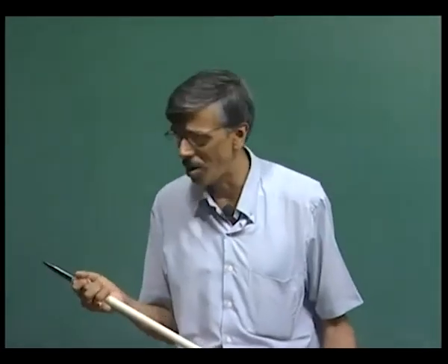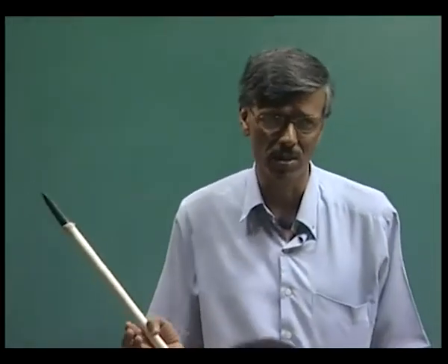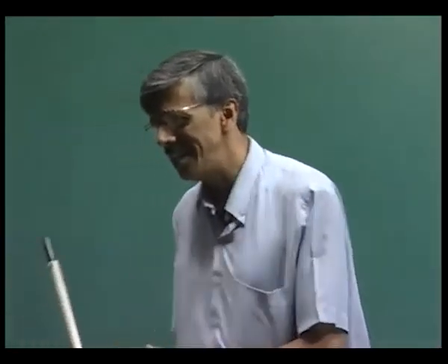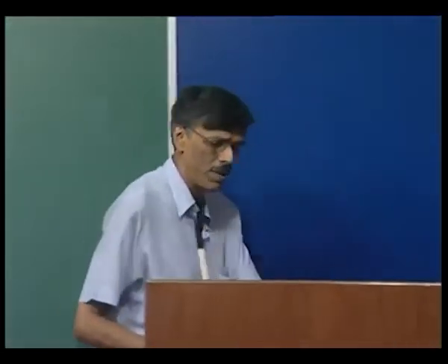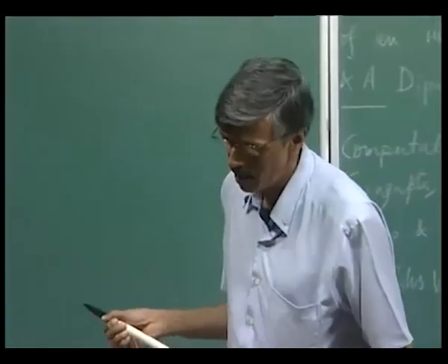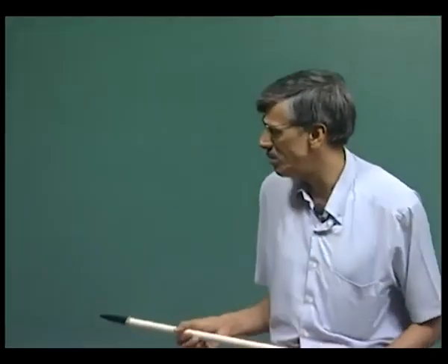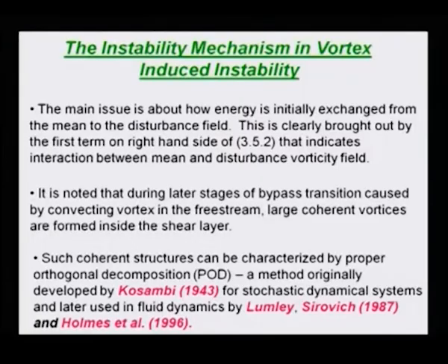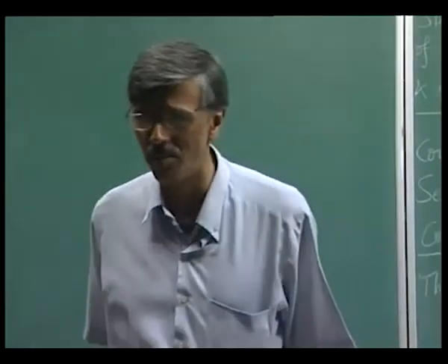This is what Kosambi thought about, and he said that let us try to look at the dynamics of the system and try to project it in a deterministic basis. So, this is rather important. It is basically a projection of a stochastic system onto some deterministic basis functions, and these deterministic basis functions are orthogonal, and they are basically denumerably infinite. So, if you are looking at a truly continuum system, you will have a very large number of them.